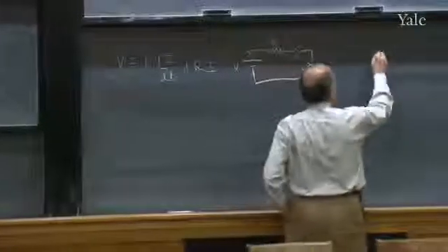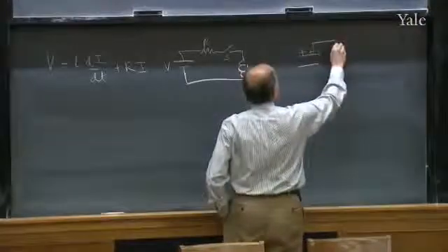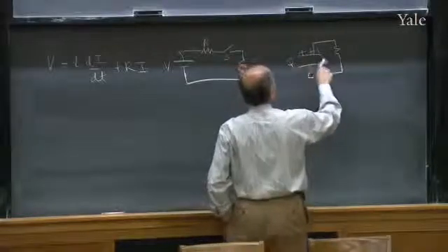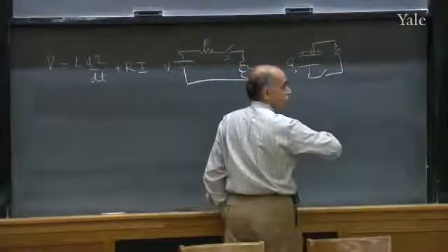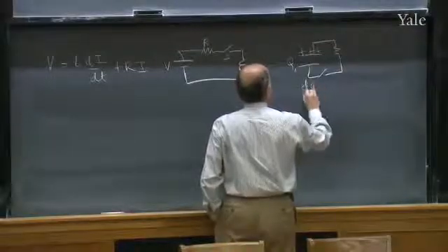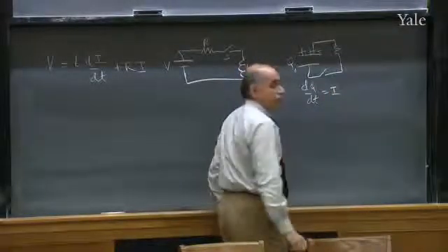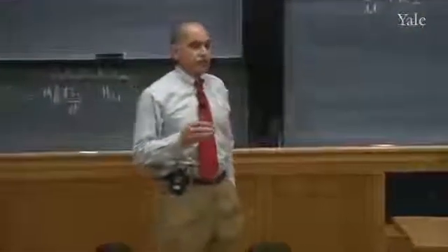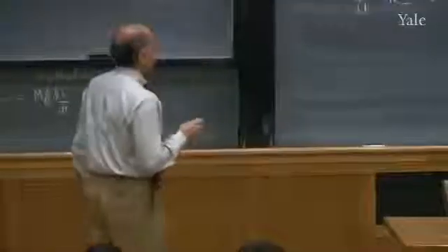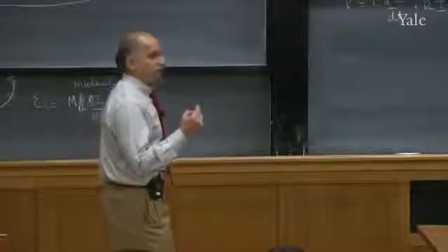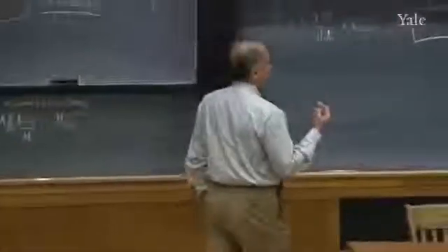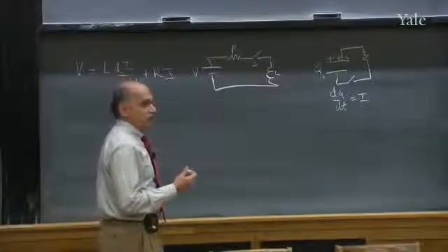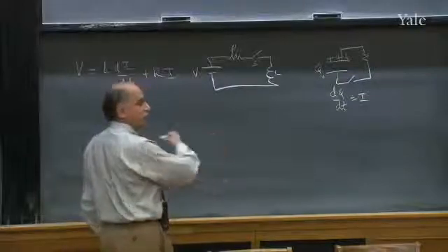Likewise, if you have a capacitor with some charge on it, and you close the circuit, the charge on the capacitor, initially Q naught, will remain Q naught 1 femtosecond after you close it, because the rate of change of the charge is the current, and the current is finite in any real problem. So capacitors cannot abruptly change the charge they have, and inductors cannot abruptly change the current they carry. And if you want, they are connected to energy. The energy in the capacitor is Q squared over 2C. Therefore, if Q changes abruptly, the energy changes by a finite amount in infinitesimal time. Nobody can deliver that energy or take out energy at that rate.